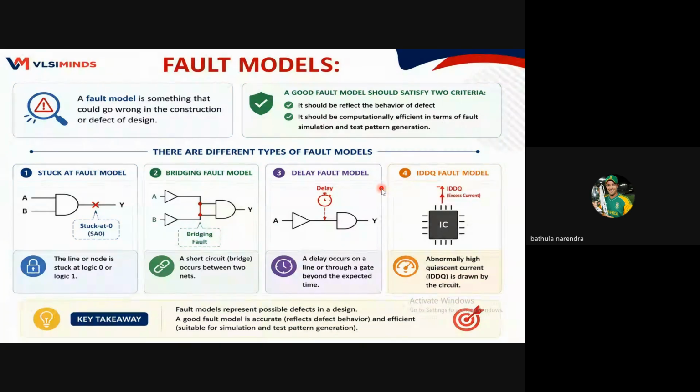One doubt: generally, after tape out we need to test a chip, right? First you do SAF, stuck-at faults, and after that we go on. Correct. First we do stuck-at faults, at a lower frequency, so that we can check that the design is okay and the connectivity checks are all fine. Then we go with at-speed, meaning high frequency testing.